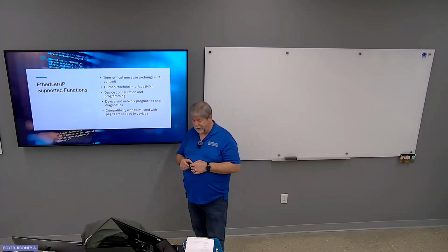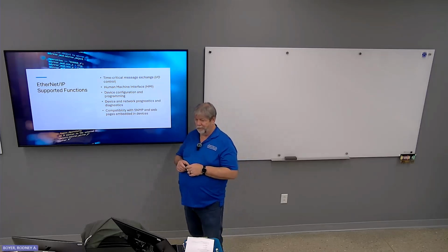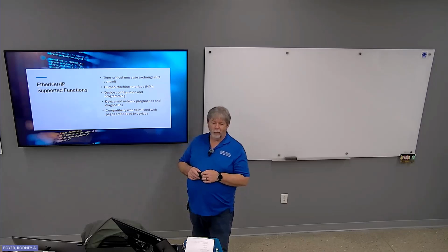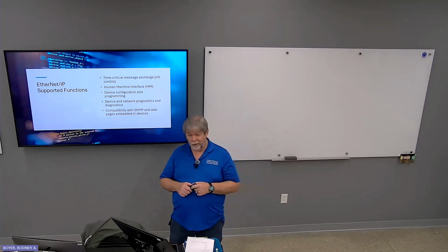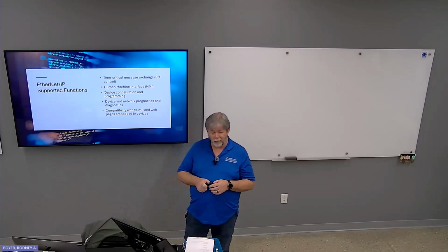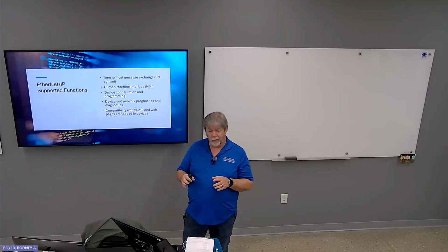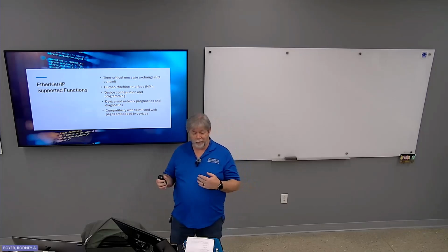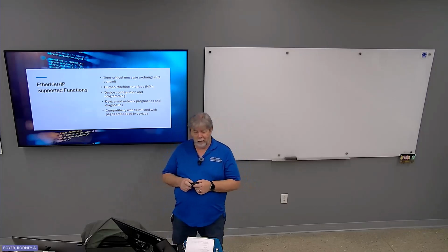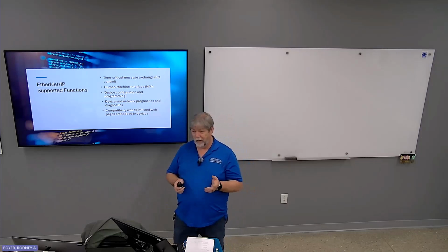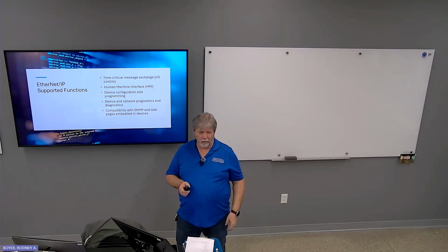But the prognostics comes in very handy because you can anticipate when things are going to fail, because there are tattletale signs. If you have a bearing that's getting ready to go out, it'll start vibrating, it'll start warming up, things like that. You can tell that it's going to fail. Sometimes if a bearing fails, it's, oh man, we had a bearing fail.